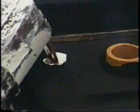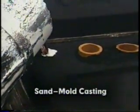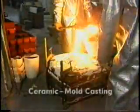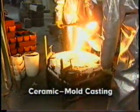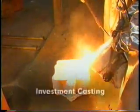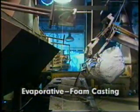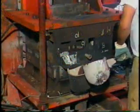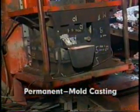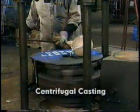Expendable mold, reusable pattern processes include sand mold casting, plaster mold casting, and ceramic mold casting. Expendable mold, expendable pattern processes include investment casting and evaporative foam casting. Permanent mold, no pattern casting processes include permanent mold casting, die casting, and centrifugal casting.